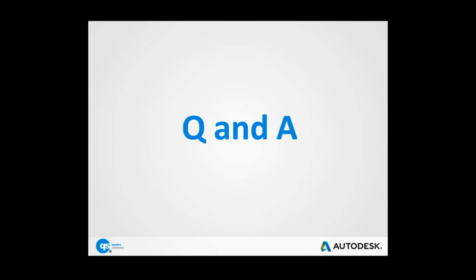Version requirements on Inventor. Sorry, I'll read the question. What are the version requirements on Inventor to be able to use Nastran in CAD? Right, it'll be year for year. So if you have 2015 Inventor, you'll need 2015 Nastran. If you go for 2016 Inventor, you'll need 2016 Nastran. Right, so the two need to be aligned. The two versions need to be aligned up. Right, okay. Question here looking through, is there a 32-bit available for download? No, it's all 64-bit. Okay, so not really releasing 32-bit then.